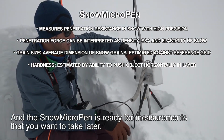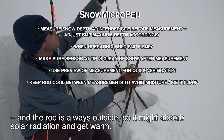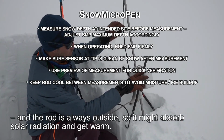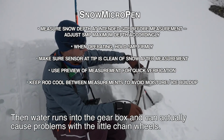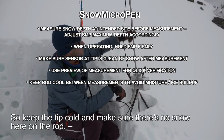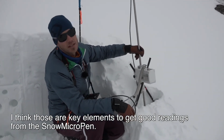If you don't do that, there might be snow sticking on the rod, and the rod is always outside, so it might absorb solar radiation and get warm, and then water runs into the gearbox and can actually cause problems of the little chain wheels. So keep the tip cold and make sure there's no snow here on the rod. I think those are key elements to get good readings from the snow micropen.